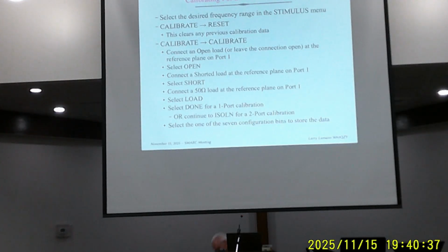But, yeah, so anyway, you say reset, and then you go up the top, says calibrate. And we'll show you the screen here in a couple of slides. So what's going to happen with that is it'll come up and it'll have open, short, load, I think what's next, the isolation and through. So it'll just come up and it'll just be kind of sitting there looking at you.